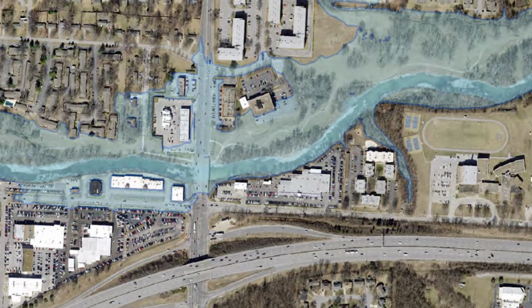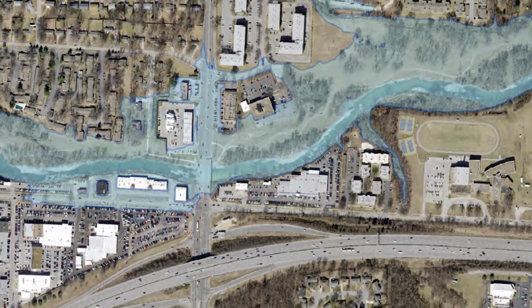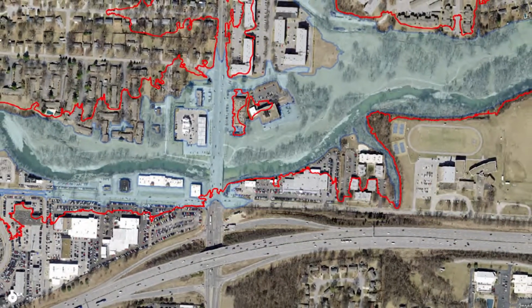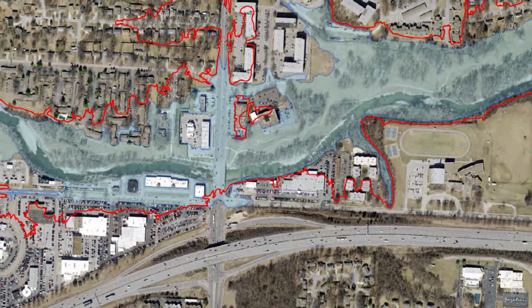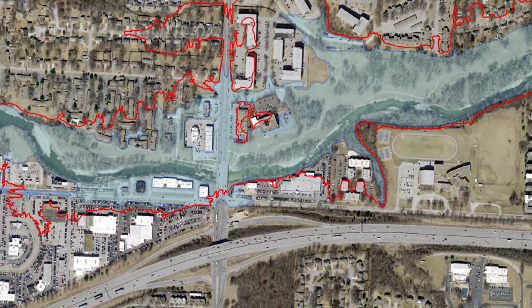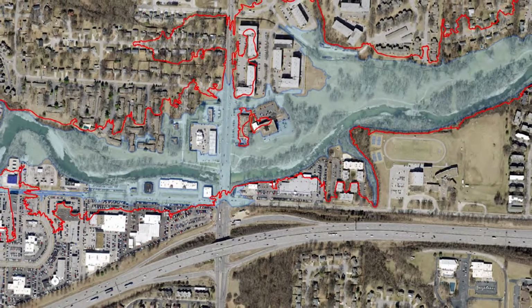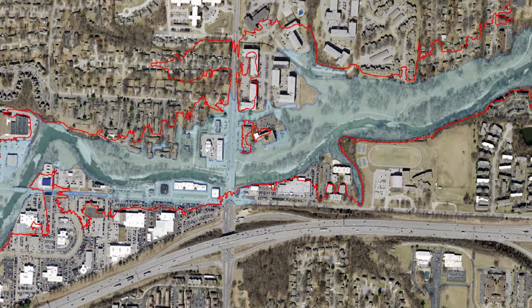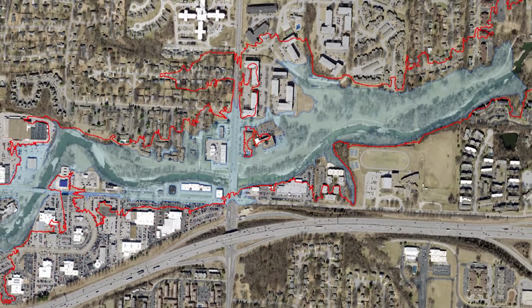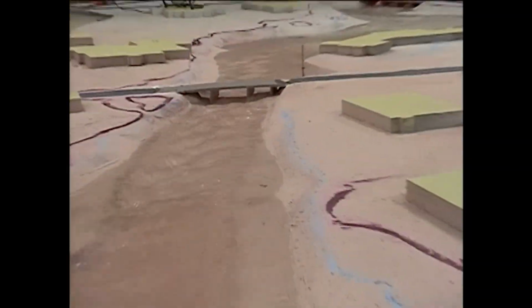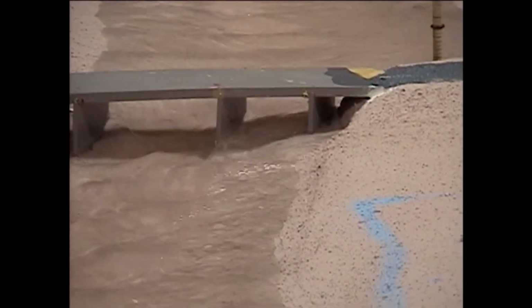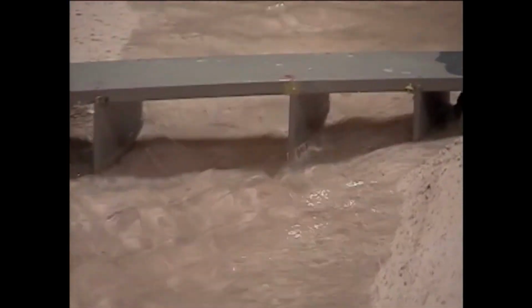In some cases, what we see is that the computer model can be a little more accurate, if you will, or more detailed. Maybe accurate is not the right word, but more detailed in its analysis. And so that can actually show some differences. But a lot of other times, the differences are that the physical model is showing those interactions with other physical features, other infrastructure, other geometries, other flow regimes that are occurring in real life that just aren't necessarily part of the assumptions of a numerical model.